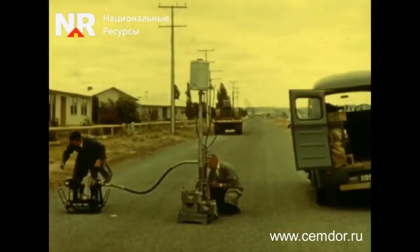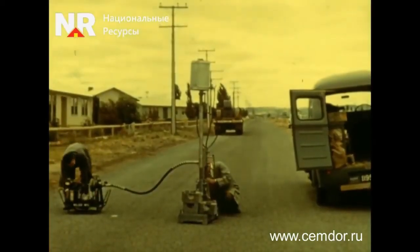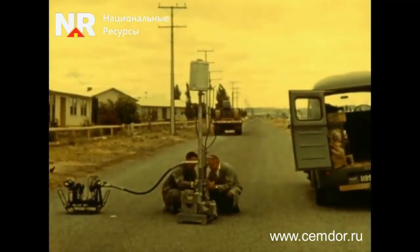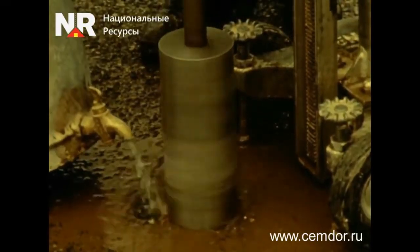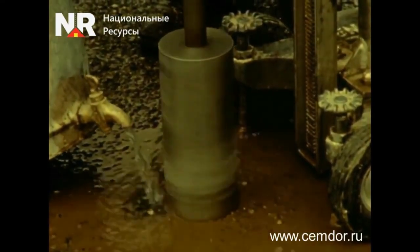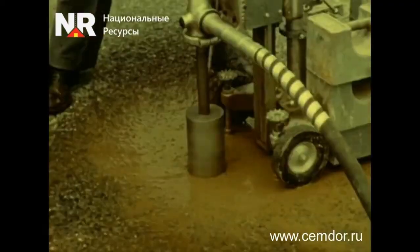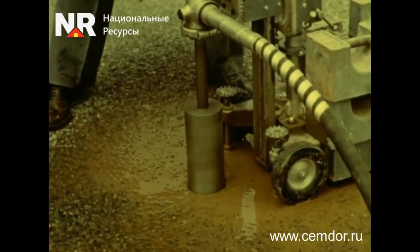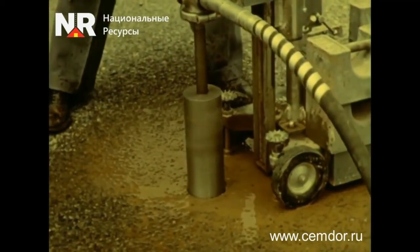A sample taken from the fully completed soil cement structural layer obtained using a core sampler is examined to confirm that the soil cement mixture will gain strength over the years and that its safety margin will also increase. This will allow the road to maintain its load-bearing capacity even as traffic intensity continues to rise.